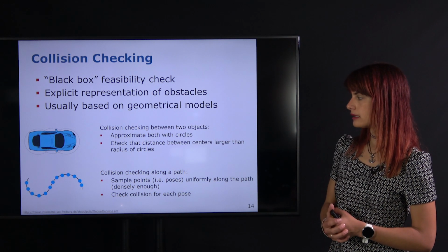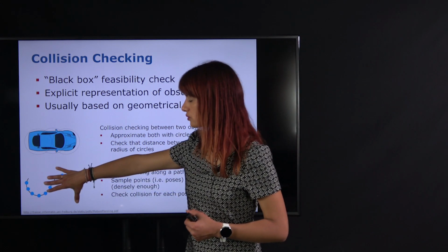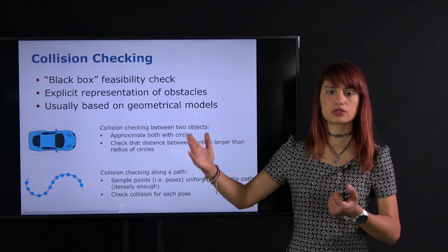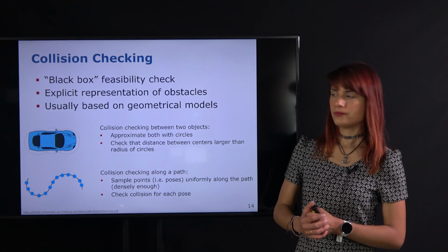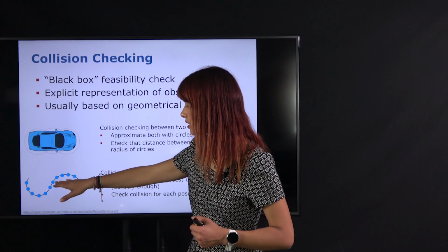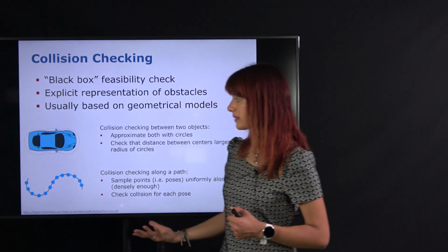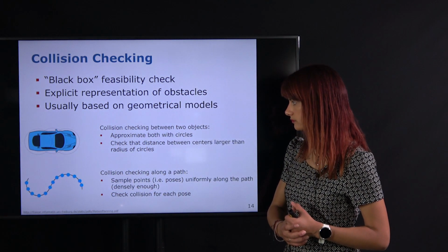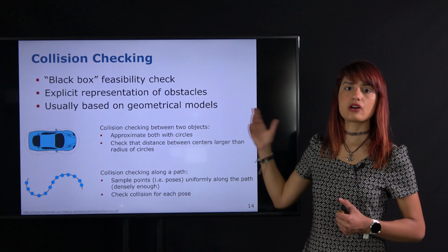And for sampling-based planning, we often talk about paths. So if we have a path, say between two nodes, what we typically do is sample the intermediate points between these nodes and check if they intersect an obstacle. So for example, in this curved path, we look at all the intermediate points in between, we subsample it, and then we check in the geometrical space whether this is actually intersecting an obstacle. And based on this, we can get our collision checking answer and develop our roadmap.